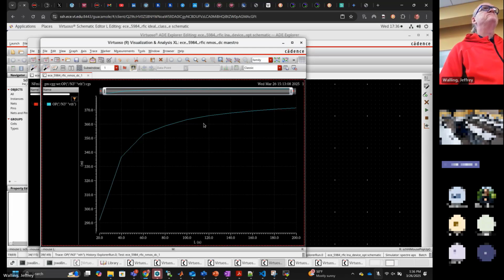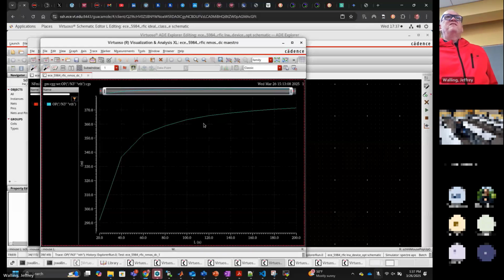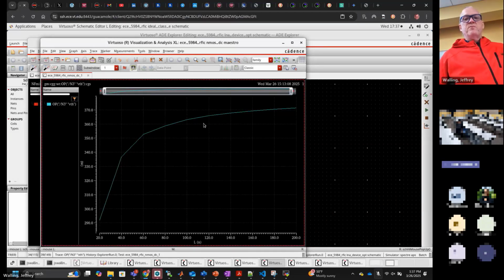Couldn't they still stress the channel by changing the drains? They do. They have non-native devices, but for the native devices, just the normal NFET, normal PFET, they have not put any dopants under the device. They're only doping in the drain and the source region. They dope under the channel to engineer the threshold voltage. Essentially, they do that in short channel devices because they need to engineer when they turn the device on and off, because they've effectively lost control of the channel, and so they're trying to regain a little bit of that with dopants.